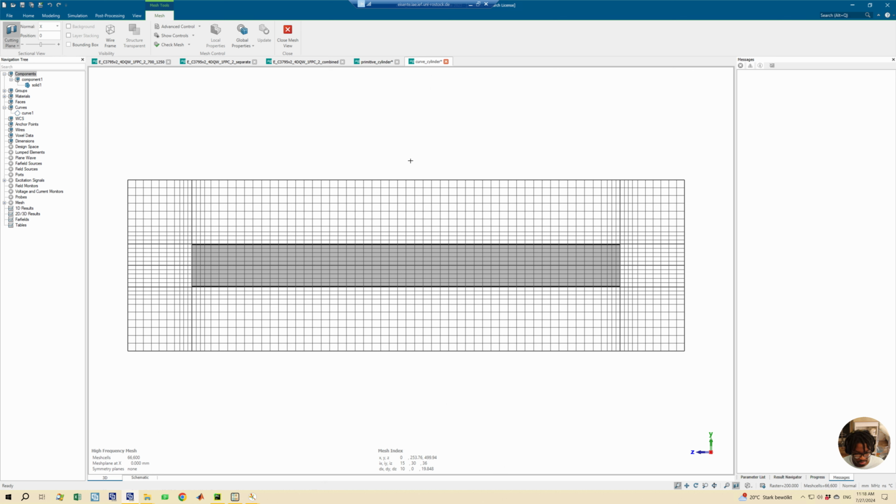So yeah, that was it for this video. For this simple case, summary, for this simple case, for tetrahedrons you have a difference, but I wouldn't say much, it's about 100 and something more for using curves. So this is also not universal again. It's not universal, it's just for this particular case, but just to show that there's a difference in the nature of the mesh generated.